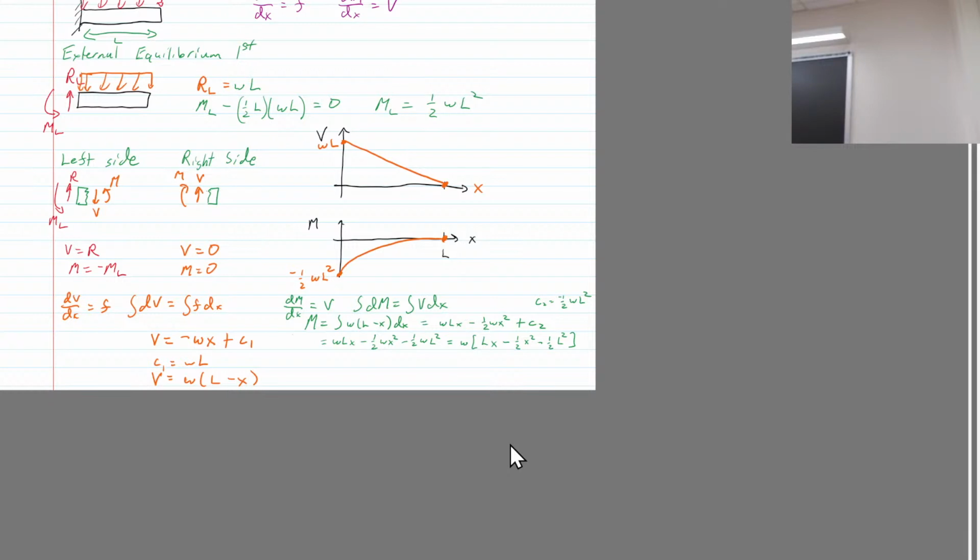So these are the contributions from Py. We identified tau T, that was from torque. Tau V is the bending, a transverse shear stress. And then there's no bending stress because, look, it wants to bend. Imagine you move Py over here, that would cause this to bend like this. If it's bending like that and this is on the neutral axis, there's no bending stress. Is it on the neutral axis?